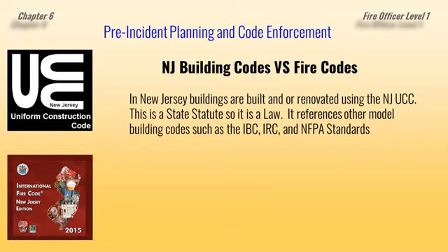So if we're going to build a new building, we start with the requirements in the New Jersey Uniform Construction Code, which is going to reference the International Building Code or the International Residential Code. So if it's a new building that's being built, it's going to be built under the IBC or the IRC.